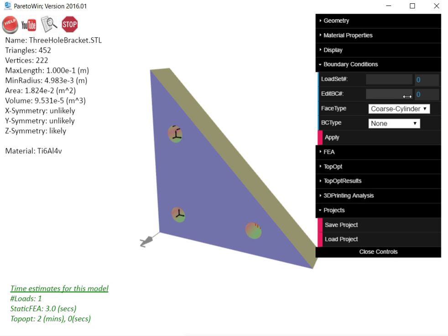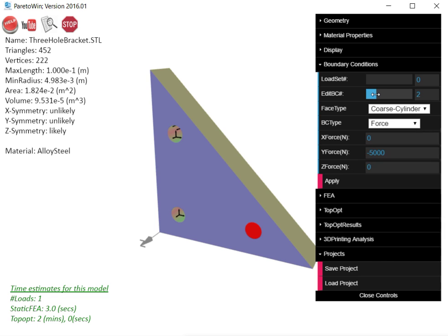Now the edit boundary condition starts at 0, and as you scroll up, the first boundary condition that we applied was number 1, the restraint on these two faces, if you recall, and the type was fixed in all the 3 directions. The next one was a force boundary condition type on this face, with the force being equal to 5,000 newtons. And if there were additional loads and restraints, they will show up as you scroll higher.